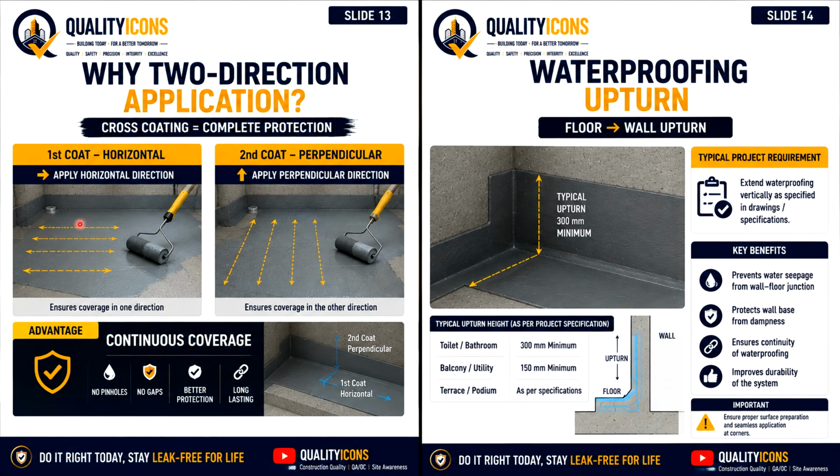The first coat is applied in this direction. The second coat is applied in the perpendicular direction. This ensures coverage in one direction, and then coverage in the other direction. This helps achieve more uniform and continuous coverage and reduces the possibility of missed areas.